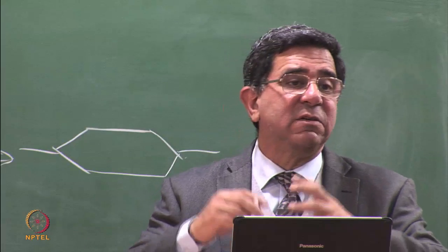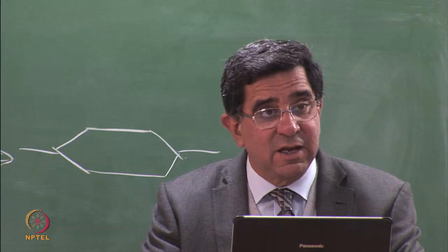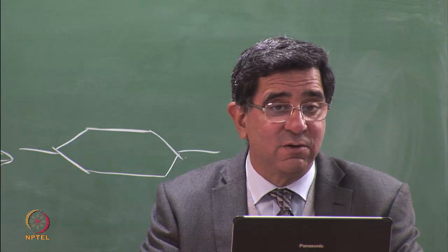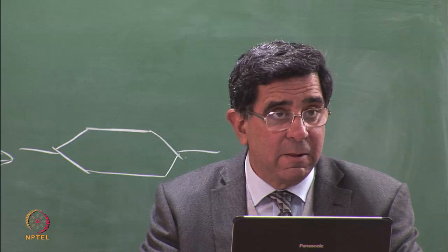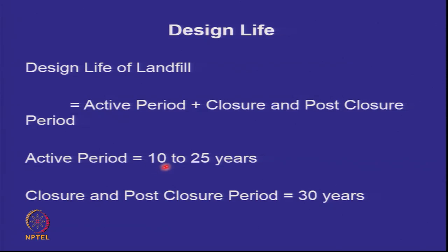All those expenditures are fixed. And if you say I'll go off the site in 3 years, you still have to monitor that site, if you're going to do an engineering design, for the full time till the waste becomes stable. So typically, a site which is less than 10 years is uneconomical or unviable. It is better to have sites which can have an active period of 10 to 25 years.